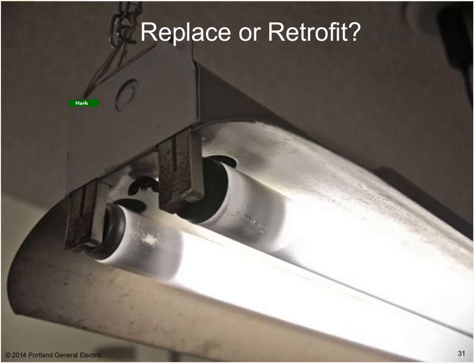Mark, what are some other types of industrial fixtures, and can those be retrofitted too? Yeah, a lot of the other type of fixtures. You might have ones that are in a hazardous location or vapor tights. You might have some that are in damp or dusty environments. Typically, those are best just getting a whole new fixture. Especially if you have a damp or dusty environment, you're going to have to replace so many parts, it's usually best to get a whole new fixture. And then there's high bays and low bays. Thanks, Beth.